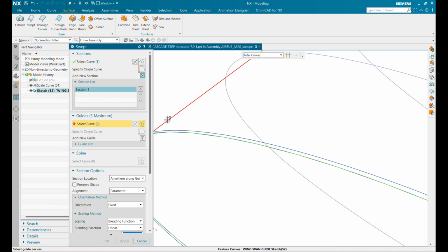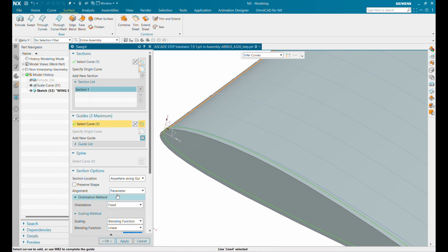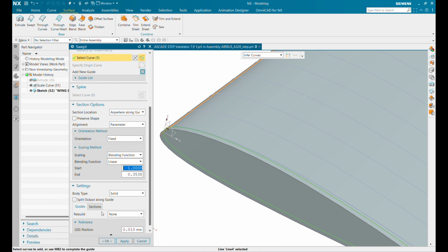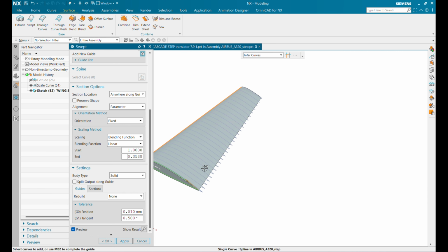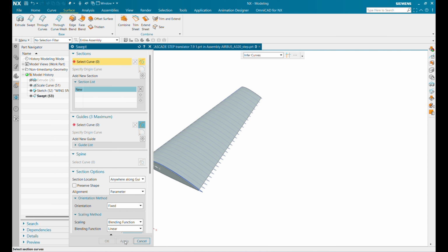Let's just hide the ribs for now. So what you see here is we will first select this particular one of the airfoils, and see this particular section here. It determines how your taper is going to behave. So what we want is it should start at the given airfoil length and should end along a taper ratio of 2.3 divided by 6.5 for accuracy.